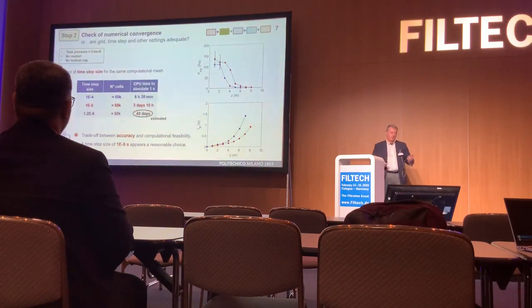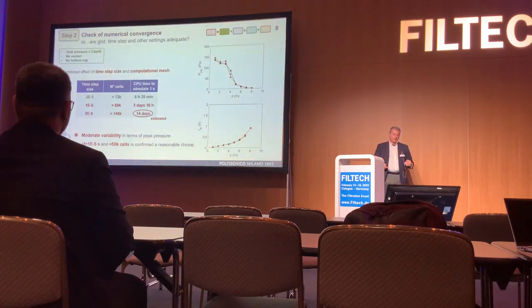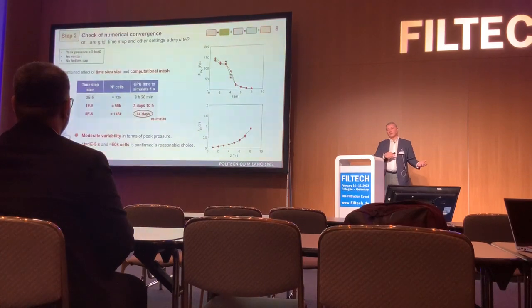So we have to face the problem of checking the variance and standard deviation of the values, and compare them with a suitable working time, especially if we want to analyze several cases. We found that a time step of 1.5 appears a reasonable choice for the model. Then we also analyzed the mesh. A very wide mesh structure for the model also takes very long, so we tried to find a good mesh that represents reality well, with a sensitivity analysis.